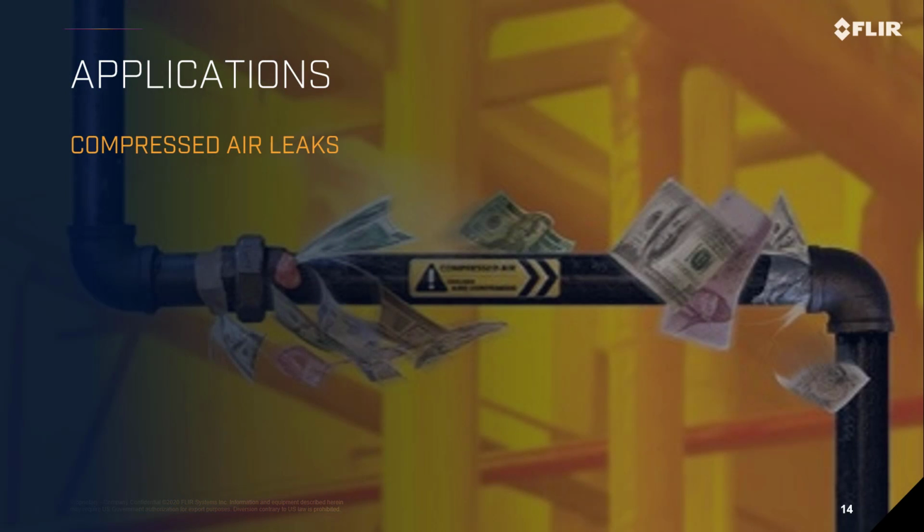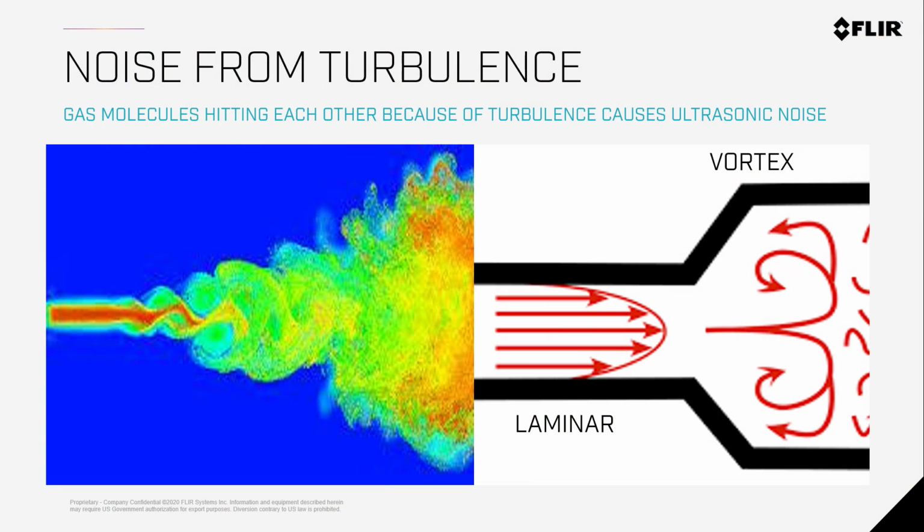So let's talk a little bit about the compressed air leaks. When the Si124 is hearing a compressed air leak, what it's actually hearing is the noise that's being generated from the transition of laminar flow of the air inside the compressed air to a vortex created when the air escapes from that pressurized container. So these air molecules bounce together, creating that high frequency ultrasound noise.